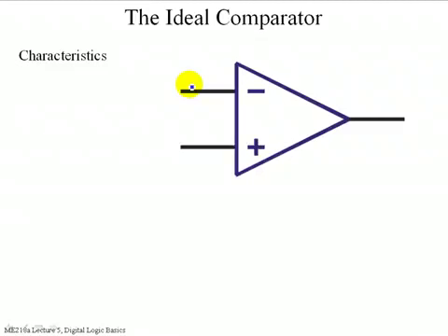What does this look like to you? An op-amp. How could you tell the difference between an op-amp and a comparator? From its schematic symbol. Pardon? Part number. Yes, if it's labeled, the part number is the way to do it. Right now, do you know the difference if I labeled this LM339? That's a comparator.